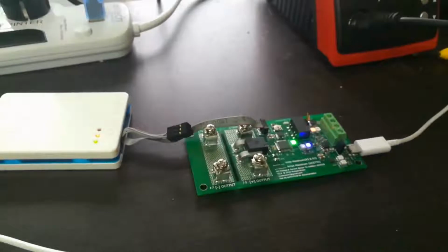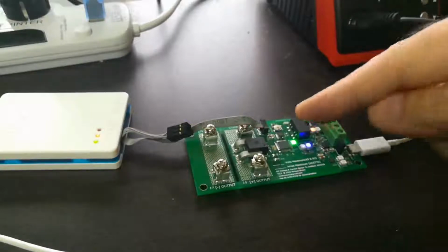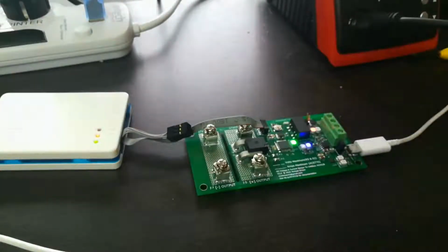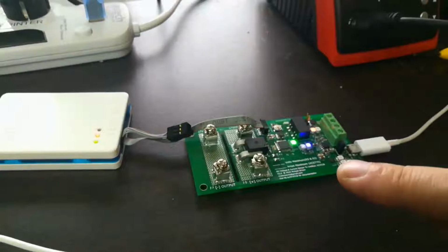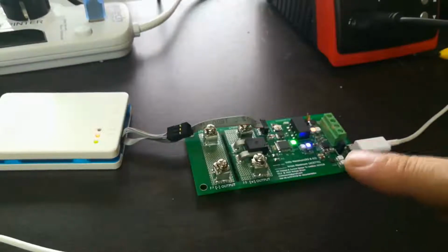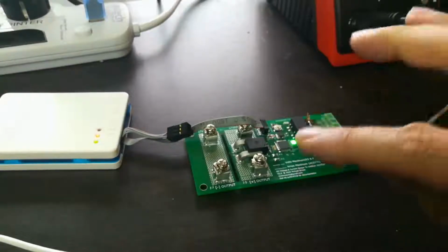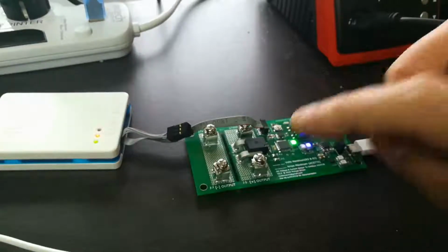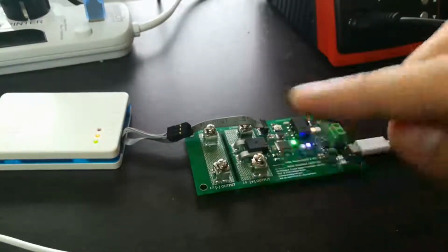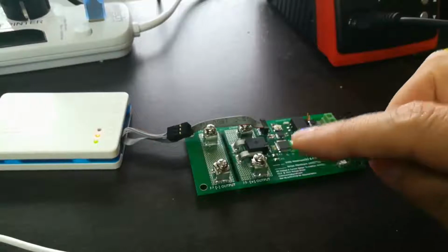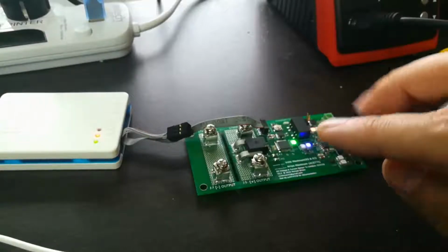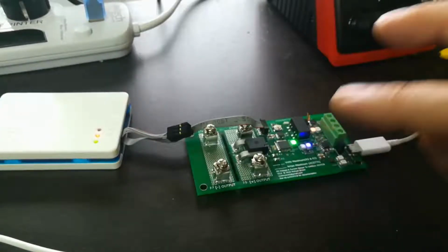Searching on the Atmel forums, it quickly became apparent that the microcontroller, if you write your software in a certain way and you put it into sleep mode, it will never wake up. And the debugger cannot get a hook into the processor to let it start debugging, upload new firmware, fix bugs. At that point, the chip is potentially dead.